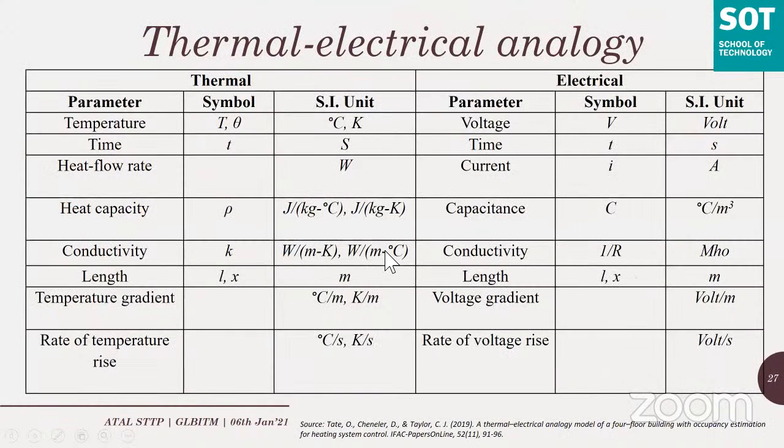Now here in our study for the grid interactive building energy systems, we develop building energy models through thermoelectrical analogy. This is very much similar, as I told you, to how for each and every equipment that we study in electrical engineering, we have equivalent circuits. Equivalent circuits usually are RLC networks, right? Similarly, every thermal equipment will also have an electrical equivalent circuit. This is because of the analogy that heat flows from a higher temperature region to a lower temperature region through a particular medium. Similarly, electricity or current flows from a higher potential point to a lower potential point.